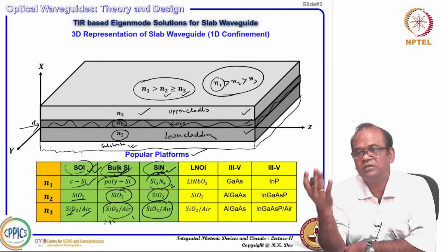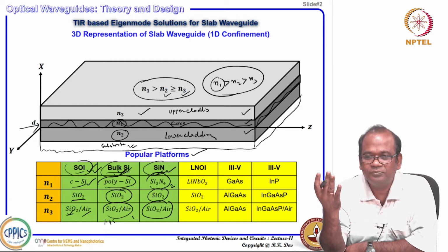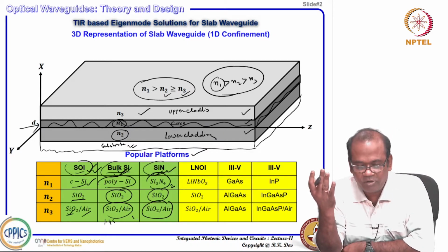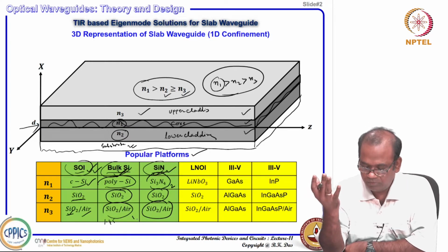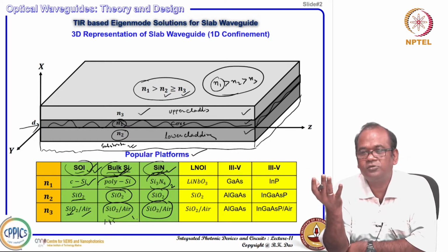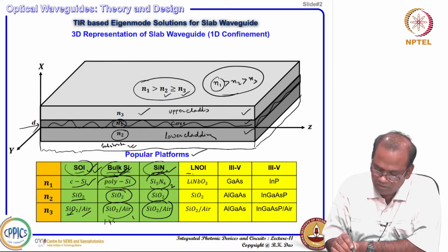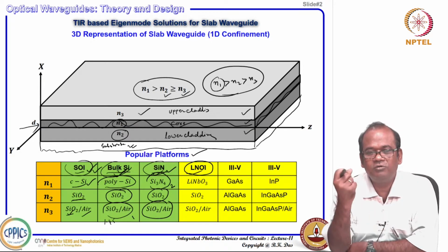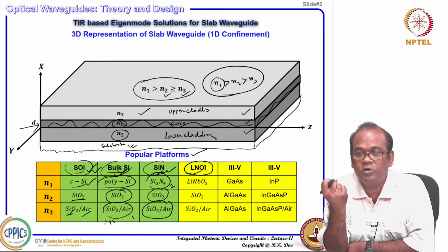You know that silicon for photonic integrated circuit purpose is not suitable for laser diode integration, and it may not be the best material for a high speed modulator. So, that is why people already explore, and are also going forward with, other platforms like lithium niobate on insulator. Lithium niobate, we have discussed earlier, is a very good material platform for high speed modulator.